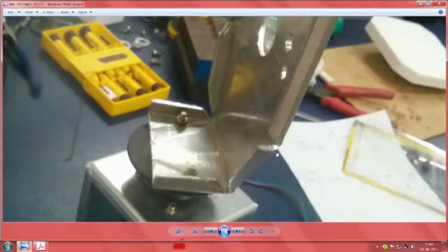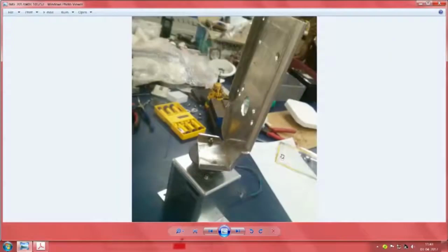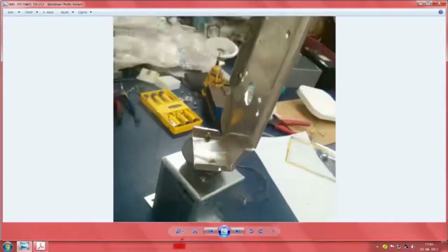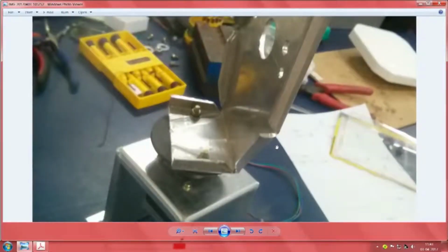This whole thing was cut out on a 90-degree notching tool, and then when we attempted to bend it, it turns out that it is not a 90-degree bend. There were some other issues with it, hence we ended up with what looked like obvious flaws in the design. These are not necessarily flaws in the design; it is just that they have all been adjusted by the constraints in production, which are specific to the machine and to the various conditions of bending and so on.